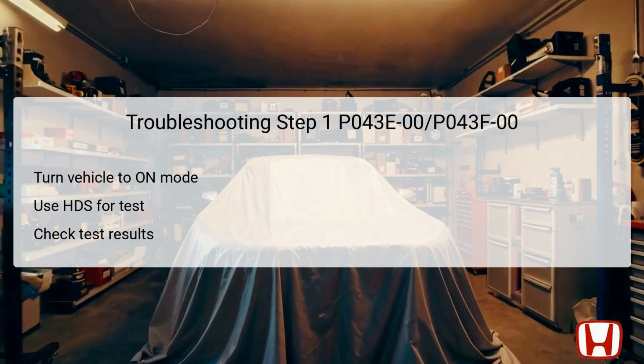This initial setup is crucial, as it allows the diagnostic tools, particularly the Honda Diagnostic System HDS, to communicate with the vehicle's control modules. Following this, running the EVAP leak check module test through the HDS will help determine the current status of the EVAP system and identify if the module passes or fails the diagnostic check.